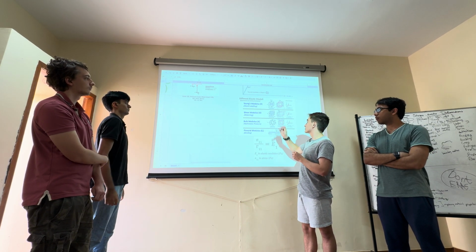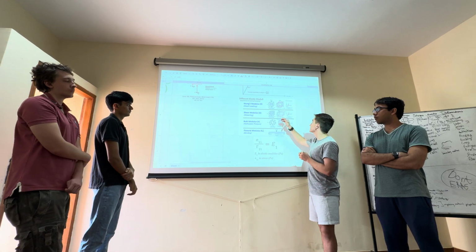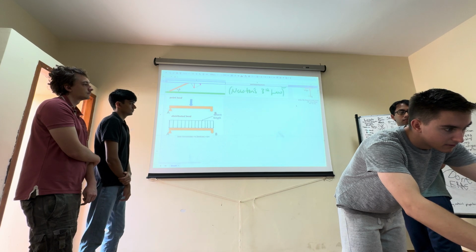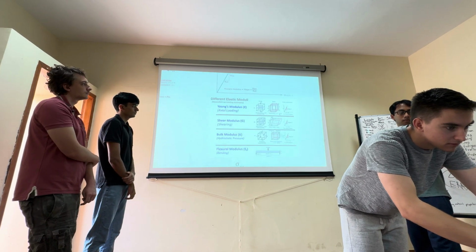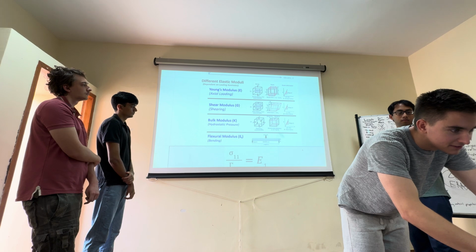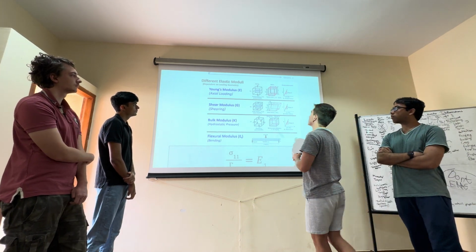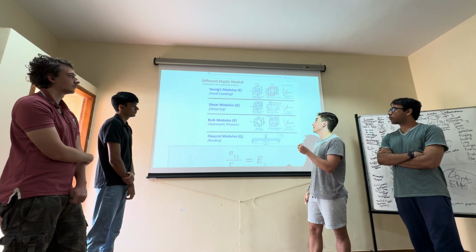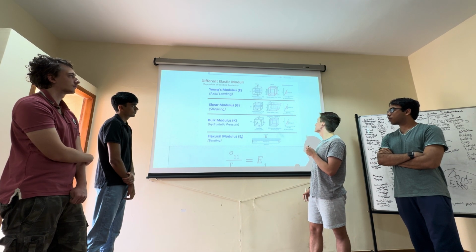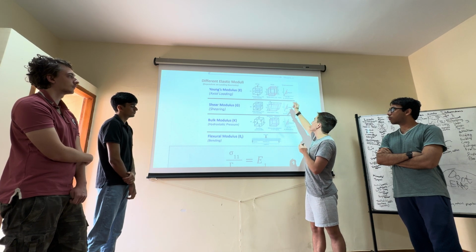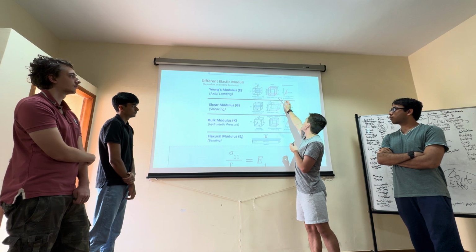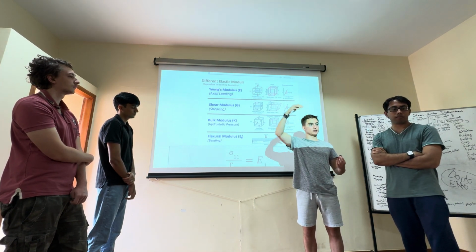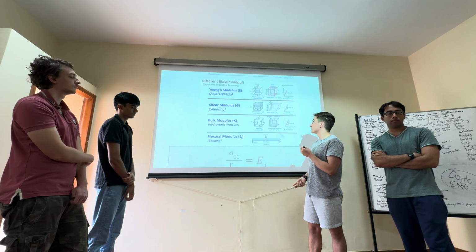So we have the Young's modulus, which is used for axial loading, and you can see in this diagram here, let me zoom in a little bit more. A little blurry, but it's a little bit better. If we're applying a force pulling out in tension on it, that's when we would define the Young's modulus, since it's in that axial loading direction. When you apply that type of load, you see this type of strain on the object. If you pull it out, you expect elongation, or if you're compressing in, that sort of deformation.